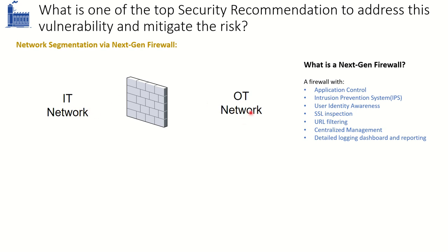And the devices on the OT network, as I said, can be very legacy devices. It can be a 10-year-old, 20-year-old PLC, which will not ask for authentication before you use it. There can be HMI workstations which will not ask for any authentication before issuing any commands. So that is the reason if an attacker gets entry into the OT network, it is very easy for the attacker to create a bigger impact there and to cause loss of human life.